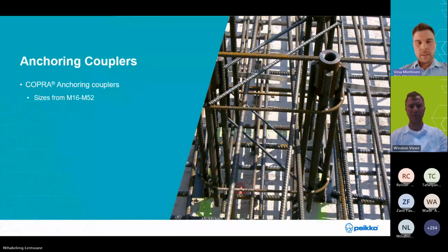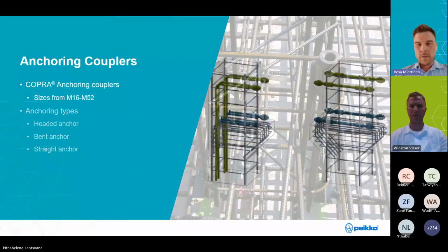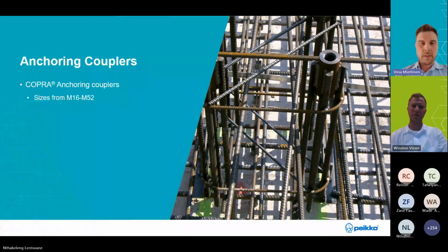And of course, the aim is to fix it properly, like you see here. For example, you can fix it properly to the reinforcement. And typically, these couplers you bolt through the formwork of your precast column, so it will stay fixed during the casting.